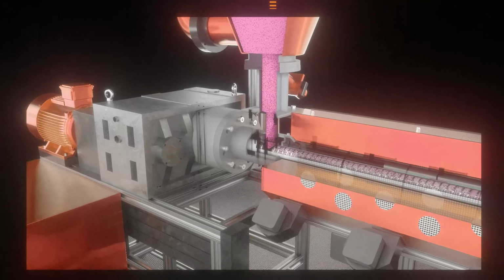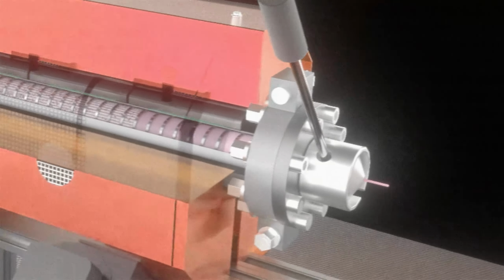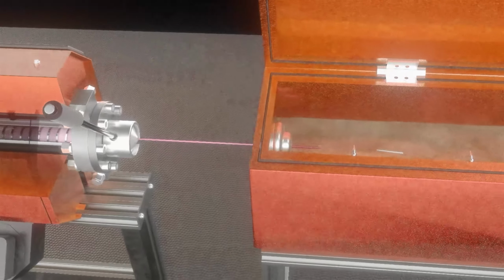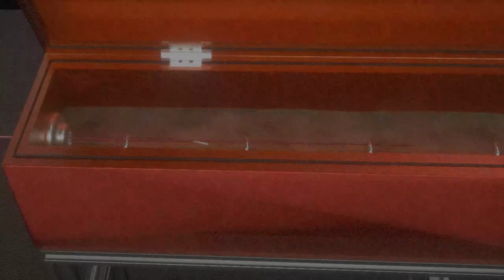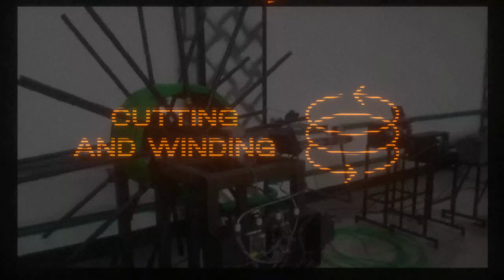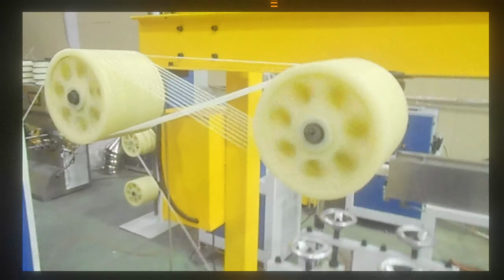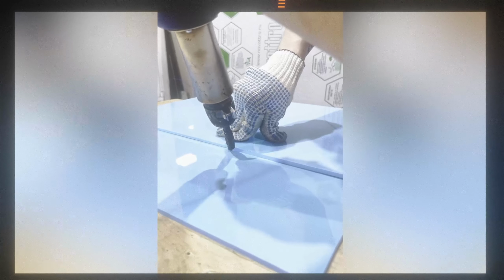2. Melting. Under the influence of temperature and mechanical mixing, the material turns into a viscous melt. 3. Product forming. Molten polypropylene is pressed through forming nozzles, creating rods, films, pipes, sheets, and 3D filament. 4. Cooling and stabilization. The resulting product passes through a cooling system, acquiring its final shape. 5. Cutting and winding. The material is cut or wound onto reels, preparing it for further use. The extruded rods obtained in this way are intended for welding the same extruded sheets.